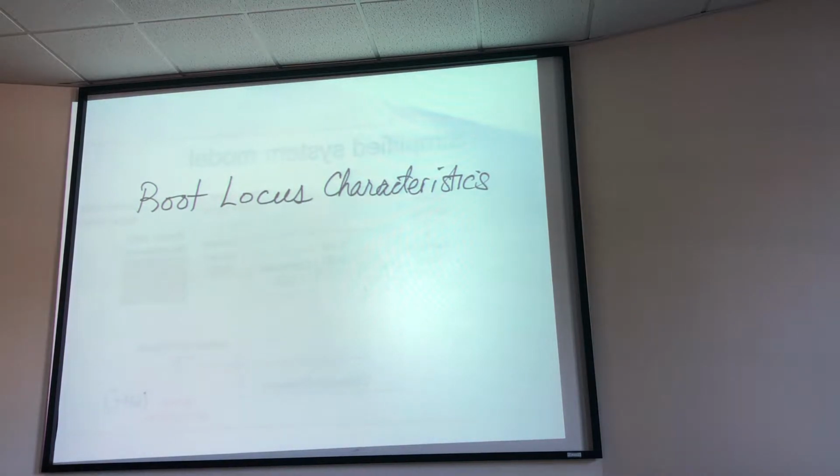It turns out that when you draw a root locus diagram, there's not a particular procedure where you have to do step 1, step 2, step 3. You just have a bunch of characteristics that need to be all satisfied. But the particular order that you do them doesn't really matter. Some of the characteristics are easy to do, so you might naturally want to do them first, but that doesn't mean that you have to. It's just that the characteristics all need to be satisfied.